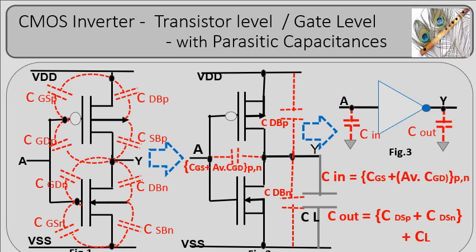CGD is the capacitance prevailing across the voltage gain terminals and is known as Miller capacitance. CGD across gain terminals can be further simplified by transforming CGD onto the input side as voltage gain times CGD. Parasitics can now be represented on the input side as Cn, the sum of CGB and voltage gain times CGD.